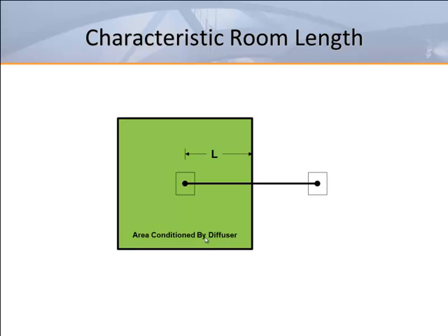While it is important to know the ADPI for large spaces, if the space is conditioned by equal spaces such as a 20 by 20 module served by one outlet, the ADPI value for that module can be extrapolated for the space. To establish the ADPI, we must know the characteristic length, or L, of the module served.